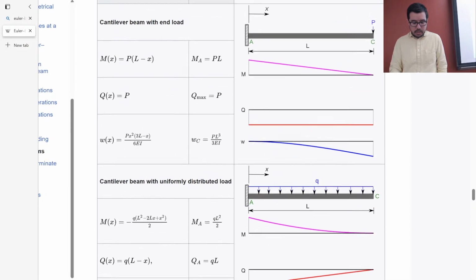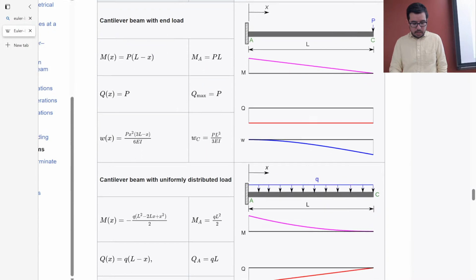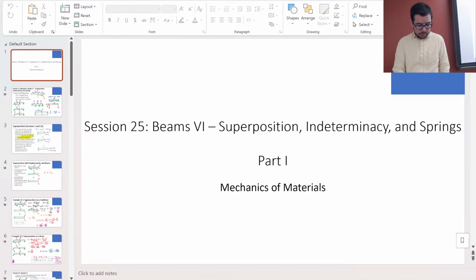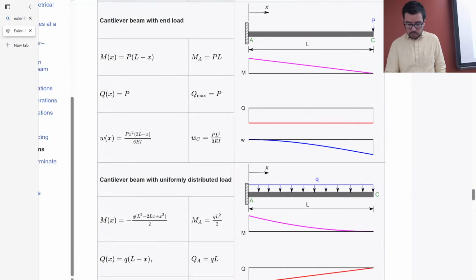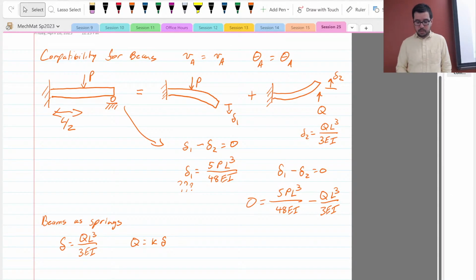Yeah. So then I was looking for, like for this case, okay. This one, yes. Oh, was I actually right? I was actually right. Huh. Okay. So the displacement delta P, with P applied in the middle, it actually is 5PL cubed over 48 EI. Did I say that? I did. 5PL cubed over 48 EI.